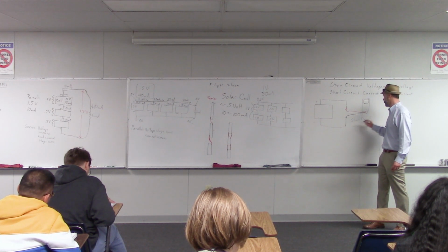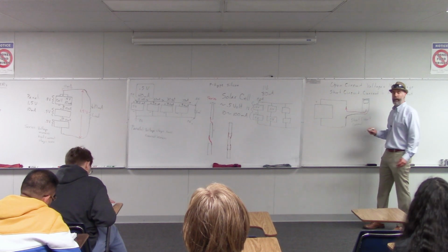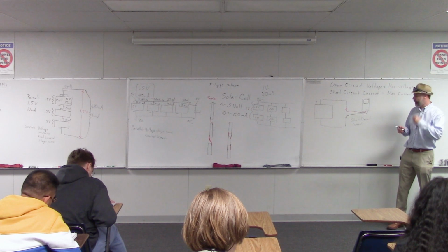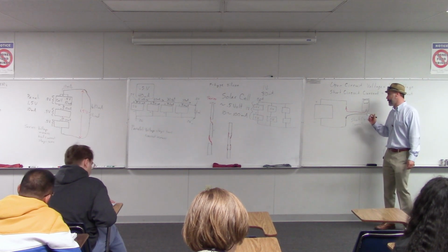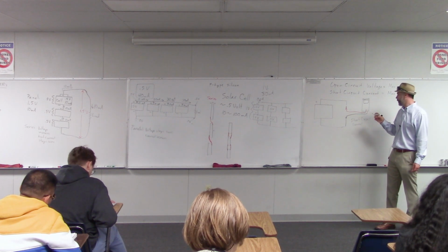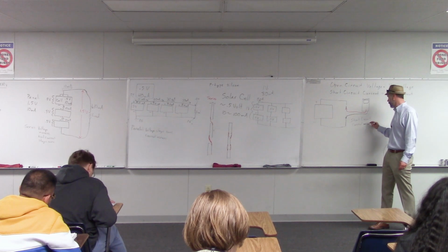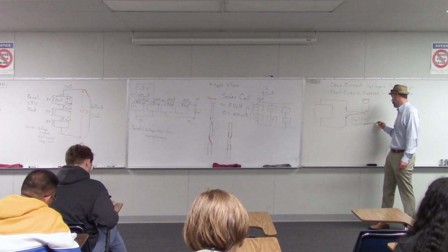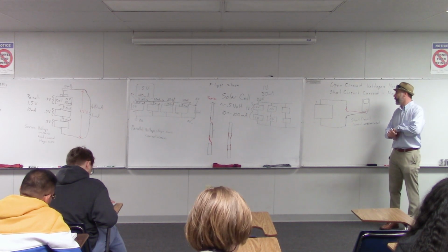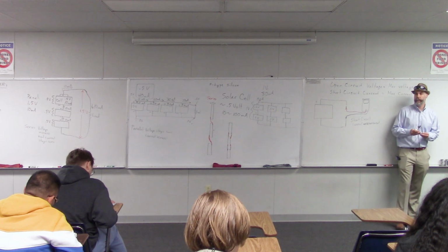Why would you want to make it short circuit? If you're trying to measure the maximum amount of current that the panel can create, this would be the maximum that it could do. Is it only okay to do that because there's some sort of resistance in the multimeter? There's actually a resistance in the panel itself. Okay. Yeah.